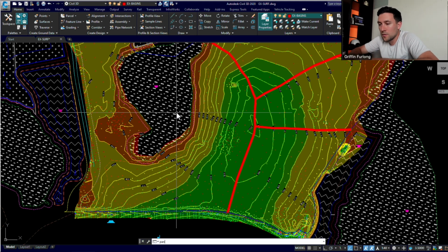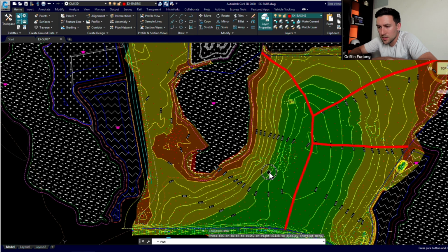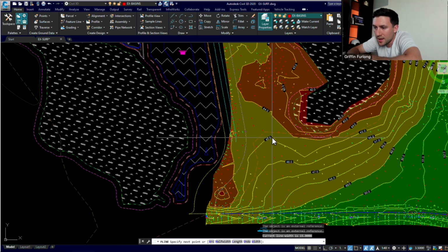And now we're going to focus on this wetland. I feel like we've delineated something good here to understand how much water flows into this wetland. And do you all see this little ridge here? I feel like there's just a little ridge right there where water wants to discharge to this open area. So I'm going to take that line right there and just work back perpendicular, and we will see where we end up.